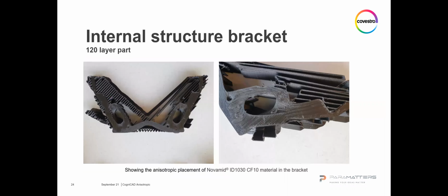This is generated, if you look at the next slide, basically due to the infill. In this picture on the right, you can clearly see how the infill is created for the anisotropic bracket, really aligning the fibers with the load path of the structure. This is not comparable to the original slicing software, which maybe takes a ±45-degree angle infill or concentric infill. It's really aligned with the load path of the structure, creating these benefits.